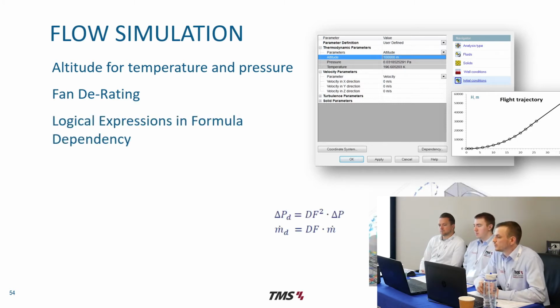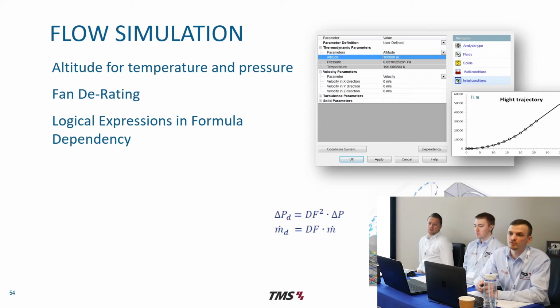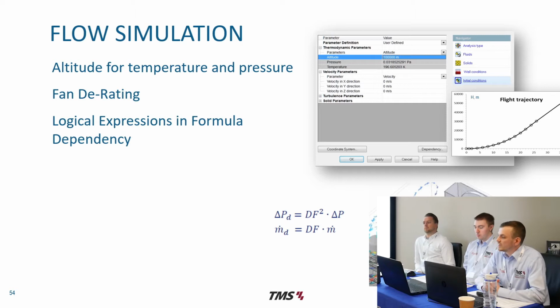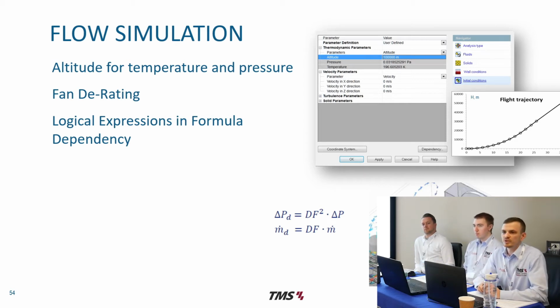We also have the ability to use logical expressions and formula dependency. Now, I can assure you that's not one that rolls off the tongue very easily, but I'll explain it. With this one, we can now control some of our inputs within our simulations, depending on some goals that we've got set up, whether that be a heat source that we've got in there, and we want to vary that depending on one of the goals. What we can do is use our ifs, ands, and ors statements in order to define these. So if your goal is below a certain value, we no longer want to use that heat source. If it goes above it, it turns on. That sort of idea.